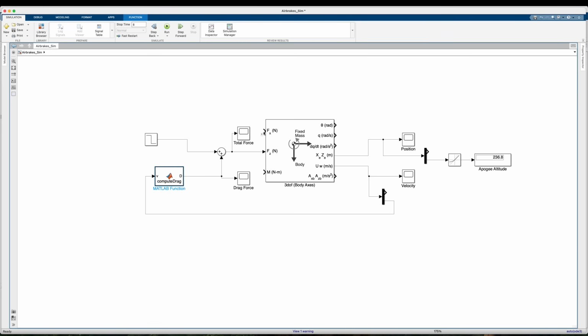We're not modeling any lateral change in position, and we're also not modeling the rocket pitching or yawing around at all. But if you're just looking to predict a rocket's apogee, if you know the motor thrust and you know its drag coefficient, this will do the exact same thing that OpenRocket does.